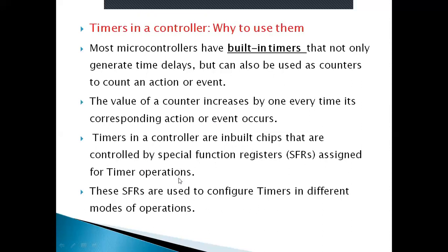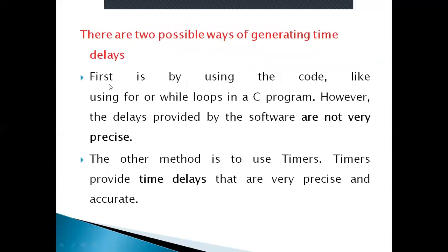We shall see what are those in the later part of this video. These SFRs are used to configure timers in different modes of operations. As I said, there are two possible ways of generating time delays. One is using the loops, another one is using the timers. So the delay generated using timers is more precise compared to the first method.